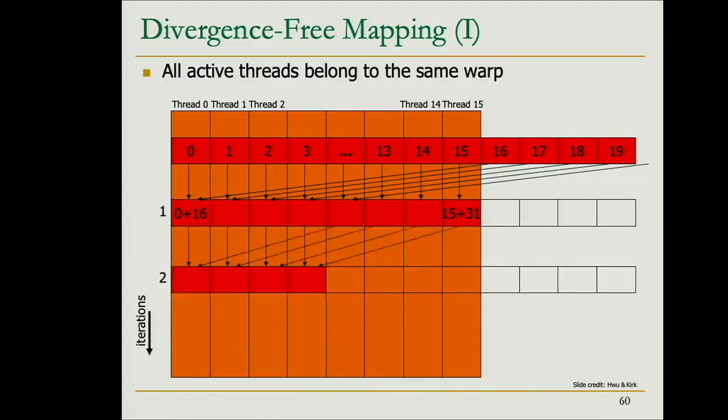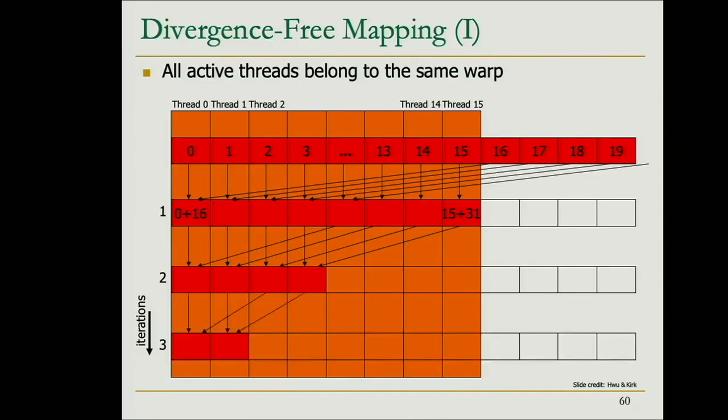In this example, you can maybe think about a thread block of 16 warps and think about warps of 4 threads. So if this is a thread block of 16 warps, I have the 4 warps working in the very beginning. In the next iteration, half of the warps retire, but the other half of the warps continue working. And inside each of these warps, or in this particular warp, I have 100% utilization because all the threads of the warp are active. And then I continue, and so on.